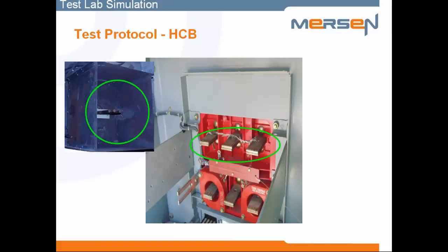This was shown to have incident energy measurements twice those of the former IEEE 1584 test configuration, where the electrodes were pointing down from the top of the box. So this would have been a worst case simulation.